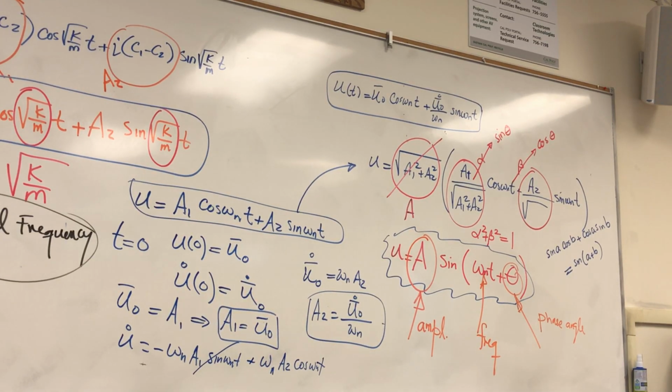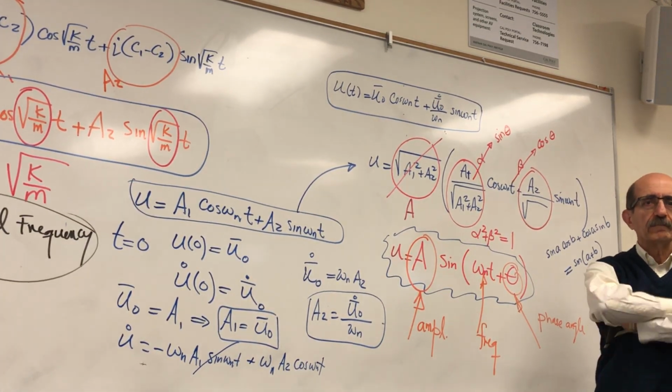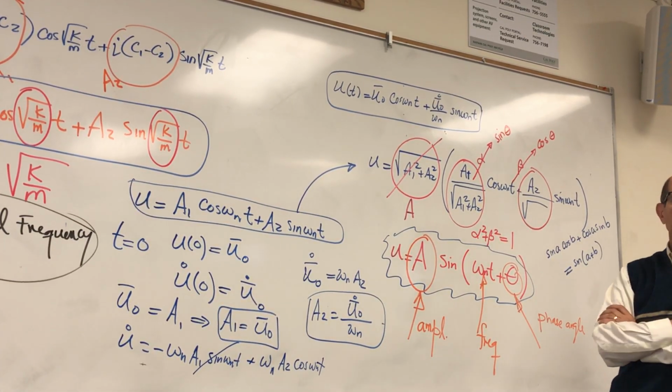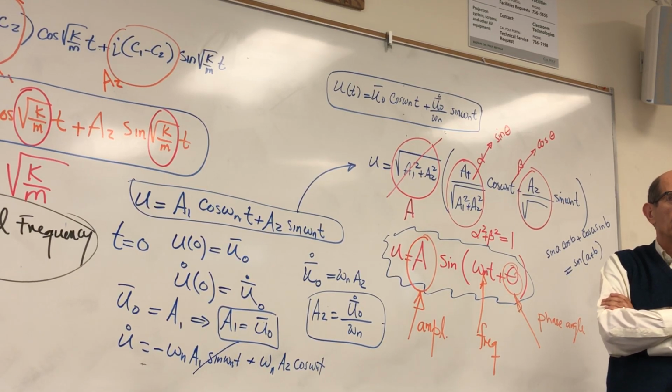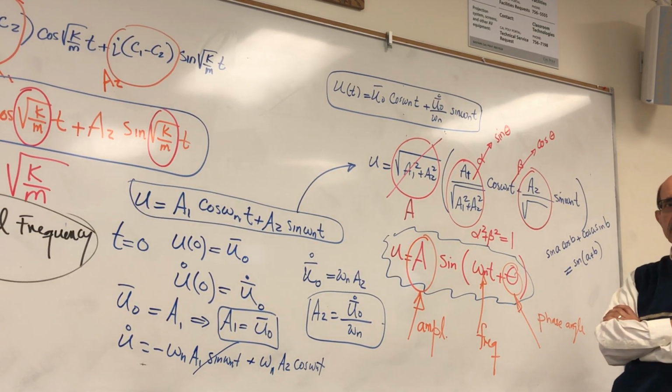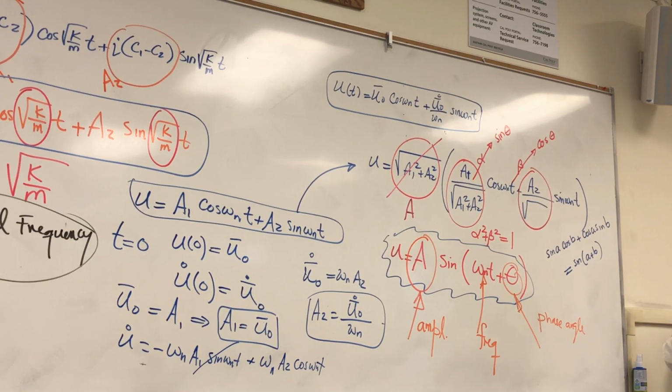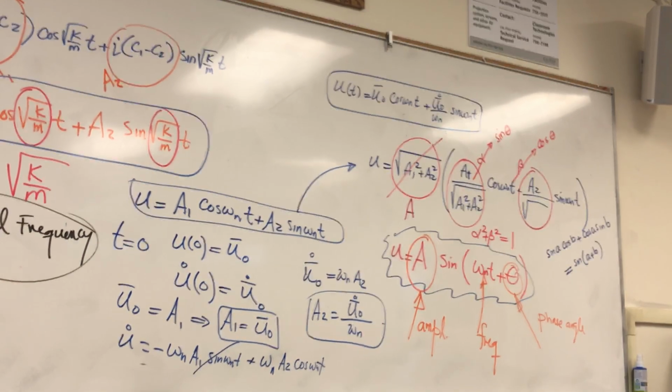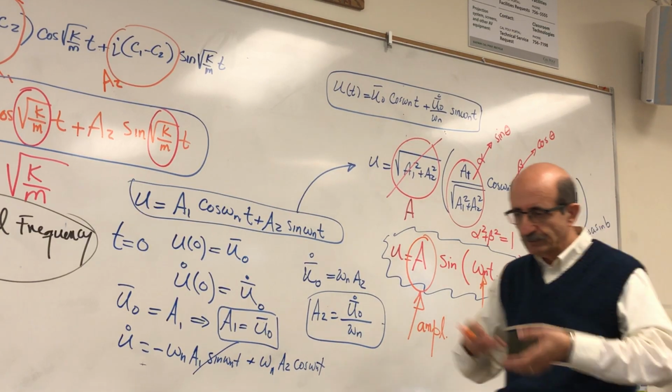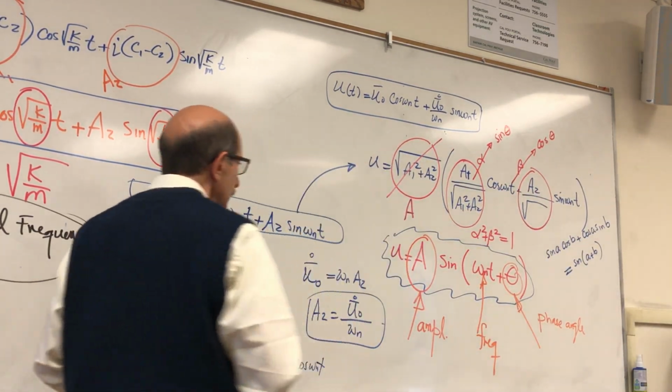But what is the amplitude? Amplitude is the maximum value of dynamic displacement, right? Because it's a sinusoidal function. So what is the maximum value of a sine? 1, right? So if you have a free vibration of an undamped system, you can find its maximum displacement. That is the value you use to find the maximum stresses and so on.